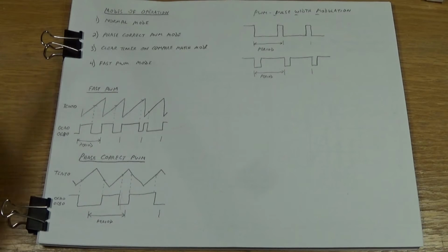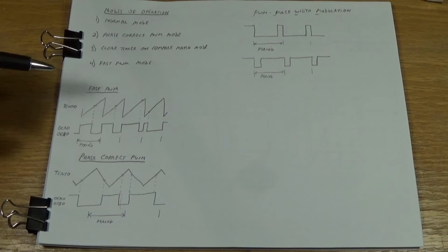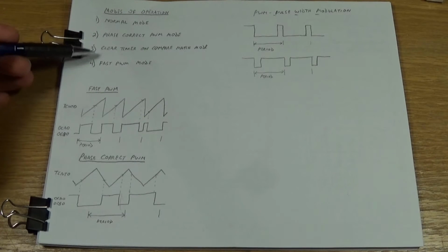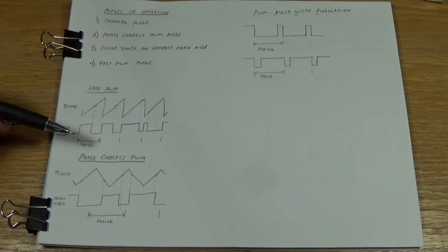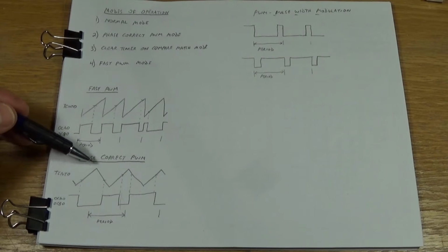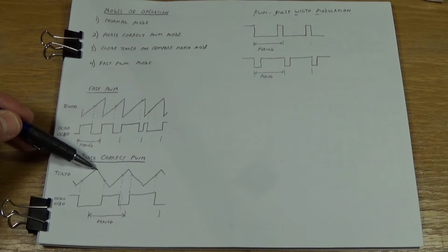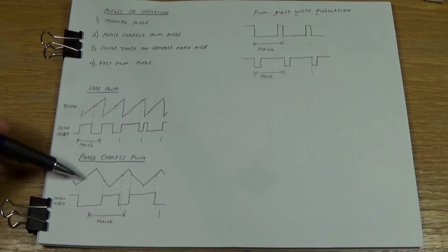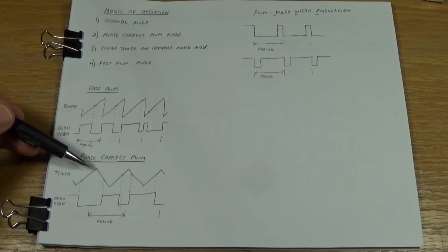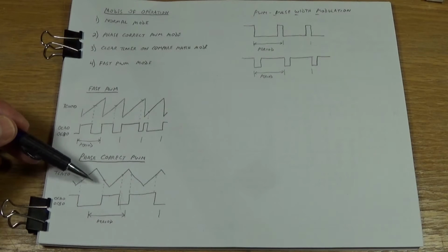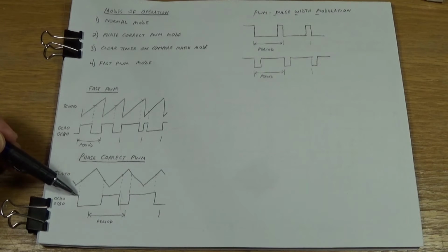So what I forgot to mention here before we go on and look at those control registers, are the 2 additional modes of the fast PWM and the phase correct PWM. The only difference is they change the value here of the top. And in the phase correct PWM mode, you use the output compare register A, and that determines how far up the timer counter register goes before it starts to count down again. And in this case, you can only get 1 channel of PWM because you're using the output compare B register to give you the time when the output pin toggles.